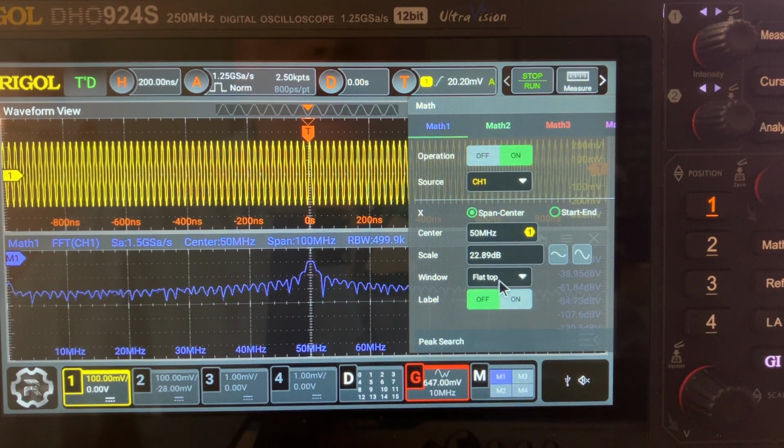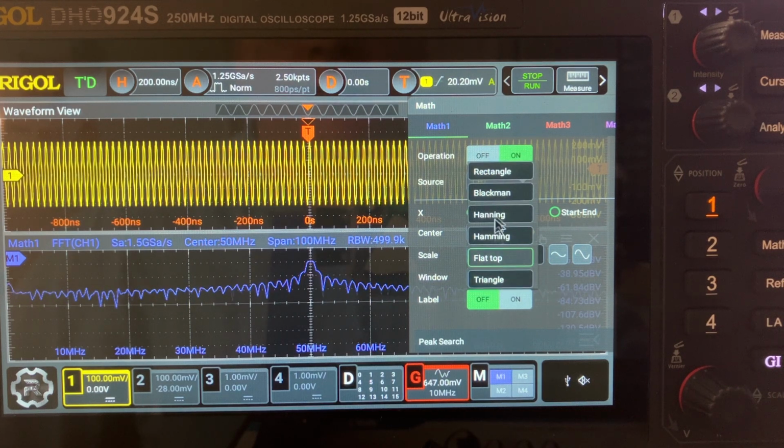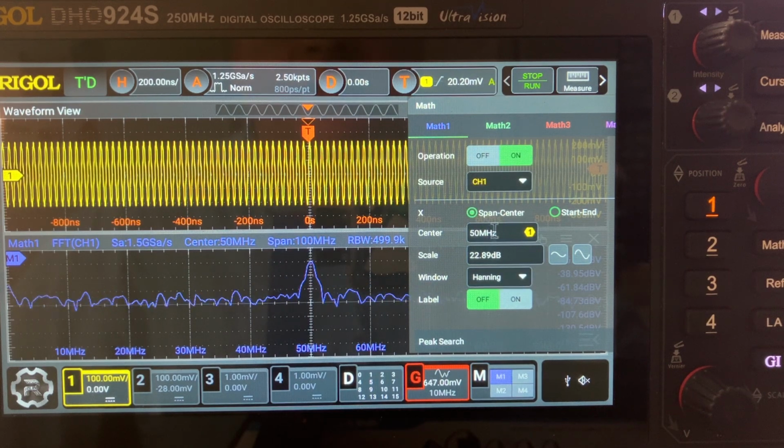They are all of them very wide. The only useful ones are Hamming and Hanning, and their objective is to find the center frequency, trying to define the peak as small as possible. So Hamming is probably the best one because it gives the least width for the peak. So if you want to identify a peak, use Hamming.